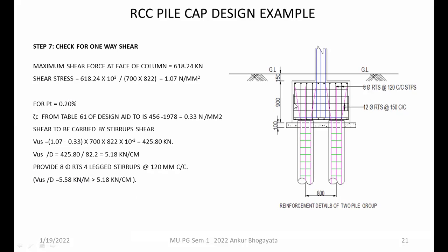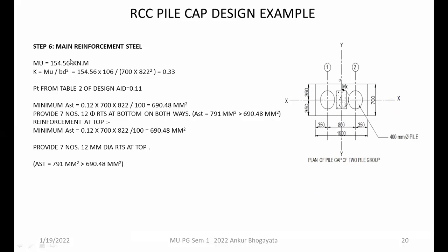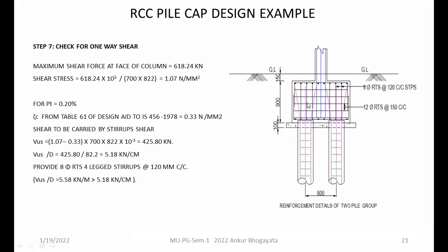Needless to add, this top and bottom steel is based on what we have calculated here in step 6, and this cage-like structure that you can see here is based on this stirrup design. When stirrups take the form of the vertical area of steel, then you can provide top, bottom, and X and Y direction steel completely in your pile cap.